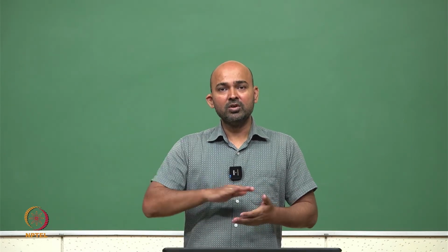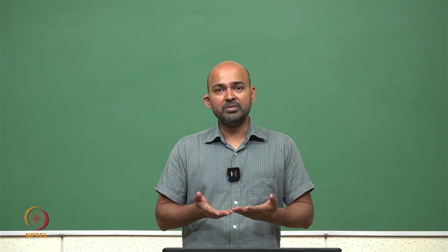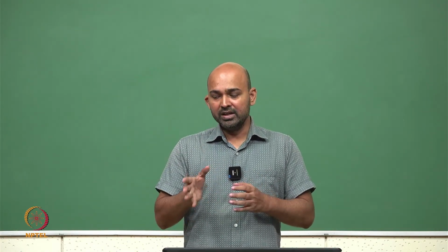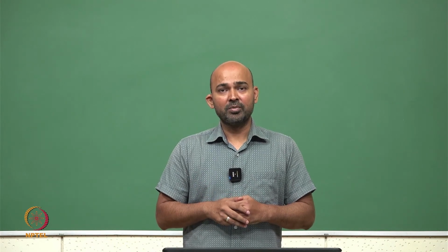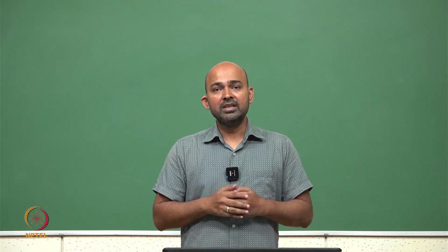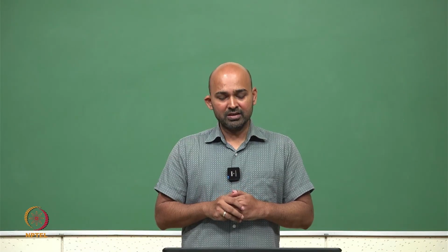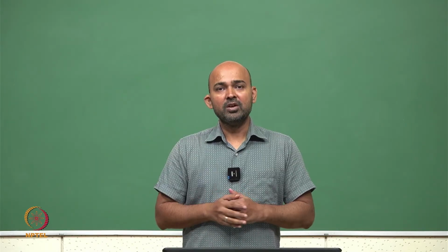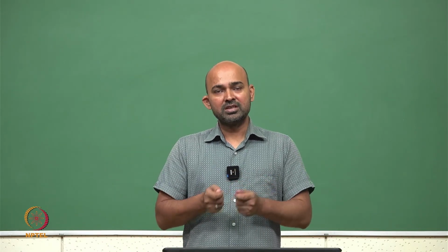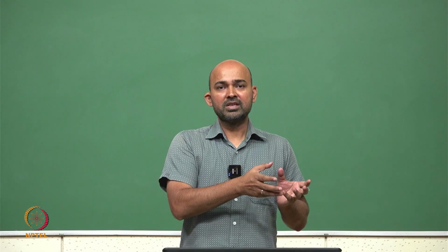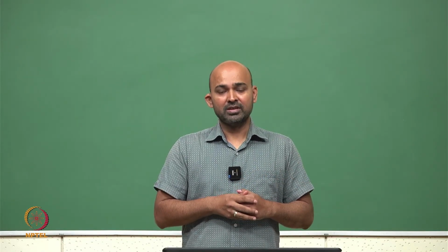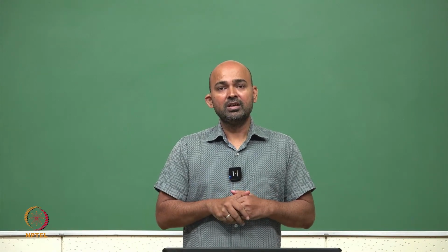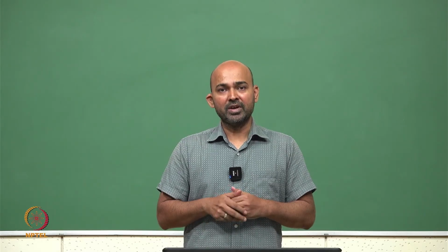So today we routed only on the front layer. It means the PCB is a single sided PCB because all the wiring we have done is only in red color, which is the front copper layer. So this is a single layer PCB which is very easy to fabricate. You can give the Gerber files which we generated to any manufacturer. They can fabricate the PCB and ship it to you. You can purchase all the components we used in the example, solder them as per this 3D viewer, and you will get your summing amplifier on the PCB.